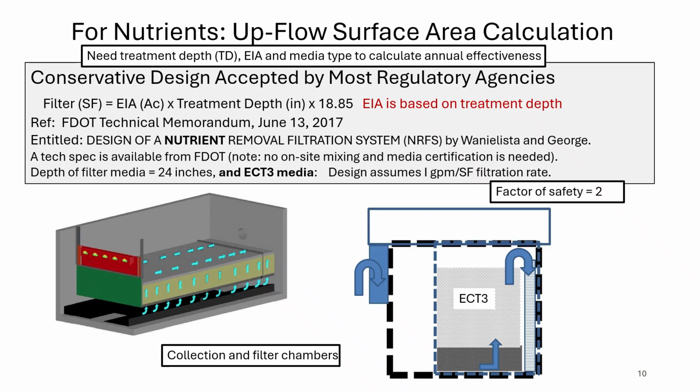This approach is considered a conservative design method, meaning it builds in a margin of safety, and it has been accepted by most regulatory agencies. The specific guidance comes from a Florida Department of Transportation technical memorandum from June 2017, authored by Wanielista and George, focused on the design of nutrient removal filtration systems, also referred to as NRFS. FDOT also has a technical specification available, and notably, no on-site mixing or media certification is required under that spec.